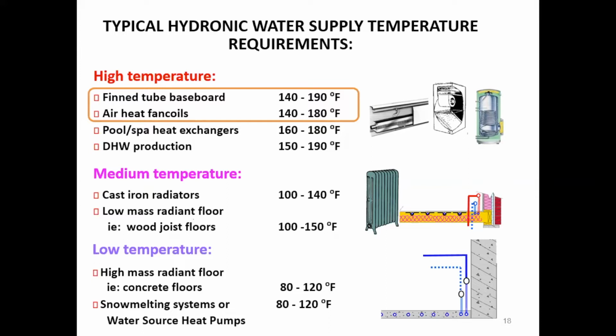The real thing is, if I can measure the outside temperature and vary the boiler water temperature based on that outside temperature, I can start to drive that water temperature down. Because frankly, design water temperatures are there for the design day. That's when the heat emitter has to put out the right amount of heat to balance the heat loss of the building. As the outside temperature drops, the need for heat drops as well. So I can modulate, I can change the water temperature, which changes the amount of heat going into the building, which will balance with the amount of heat leaving the building.